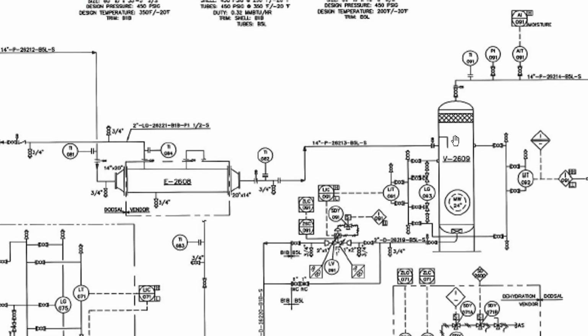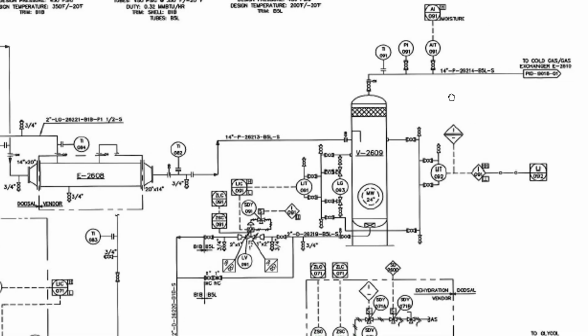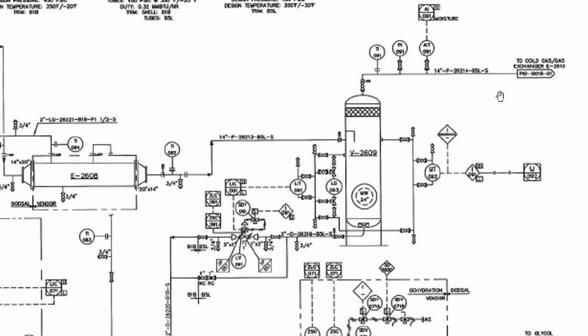It is another separate vessel which is also collecting here, and the inlet device is there collecting the liquid, including liquid amine as well, because any amine is carried over with the natural gas that is collecting here. The demister pad is there, and it is releasing H2S-free clean sweet gas. Sweet gas is released to other processes.